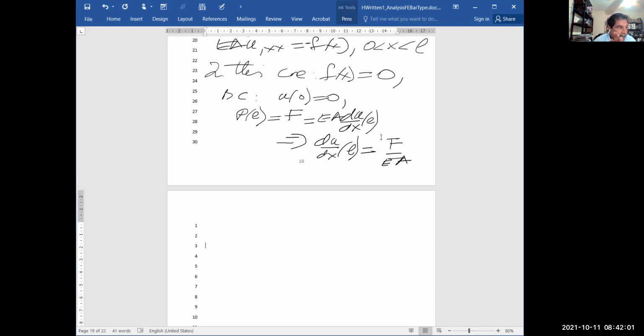Impose supports. Those conditions have to be enough in order to take the singularity away. That means that at least you have to have, in this case, one geometric boundary condition. And then you have to recognize that there are two different subsystems.